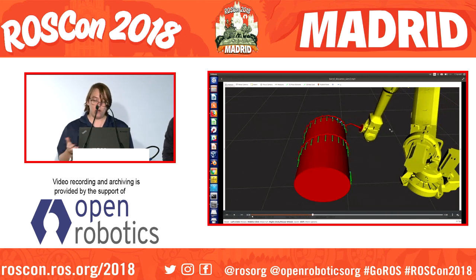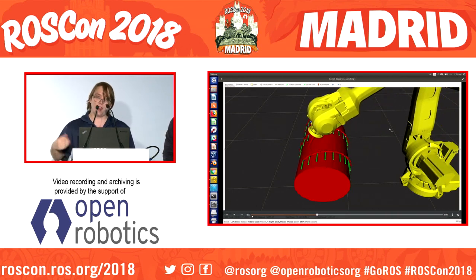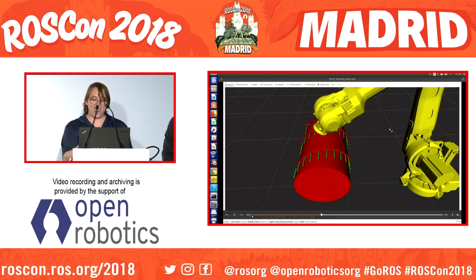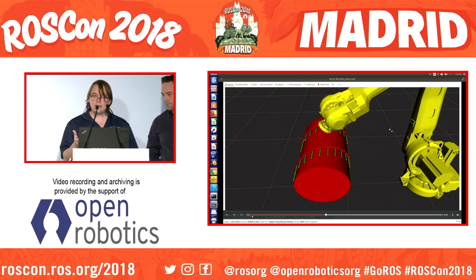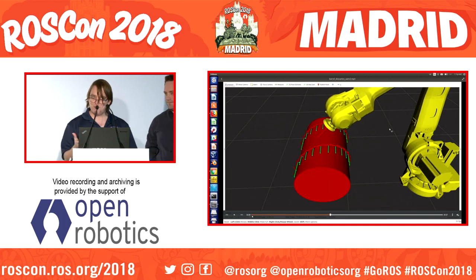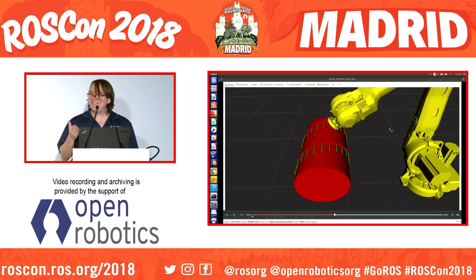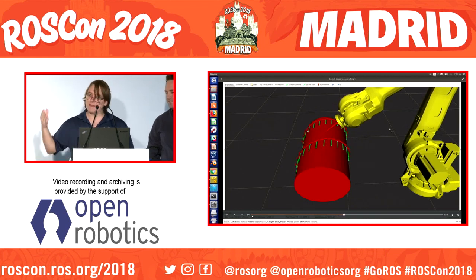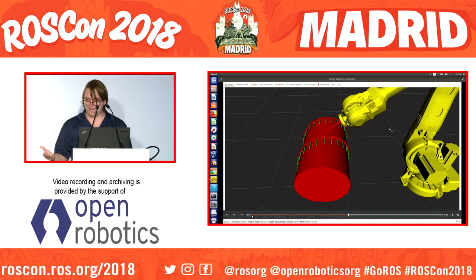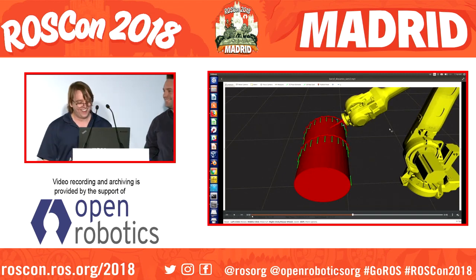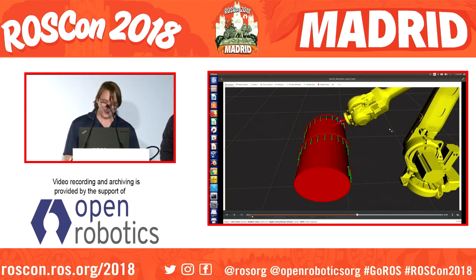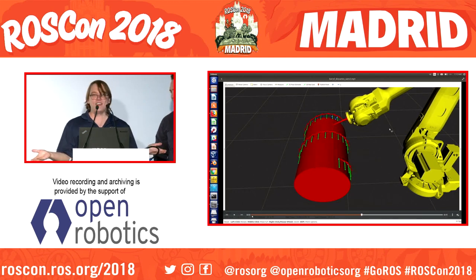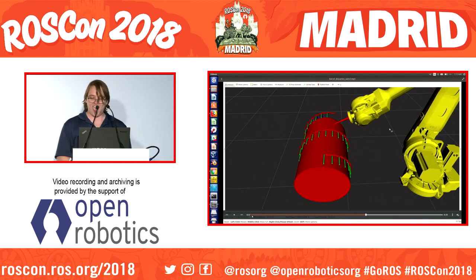And so what we do is we take the Descartes plan and run it through TrajOpt. Surprise! And what you get is this extremely boring, extremely smooth path. If I've learned anything in my time doing industrial robot stuff around things like planes, it's that boring is good if it works well. So I think you get the idea, right? Essentially, the barrel just keeps turning, and it never really accelerates except at the very beginning and the very end.